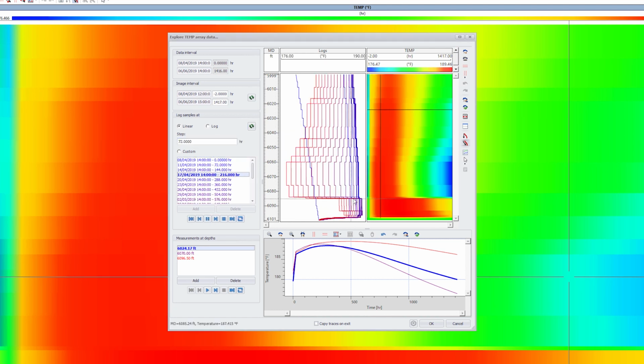At the start of production, before water breakthrough, the temperature profile indicates fluid inflows from the perforations that would be expected for a multi-layer liquid producer. At some point, a temperature drop is seen at the second perforation. Above this depth, the temperature continues to increase.